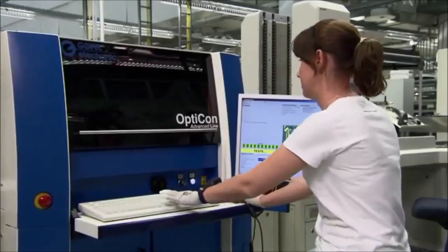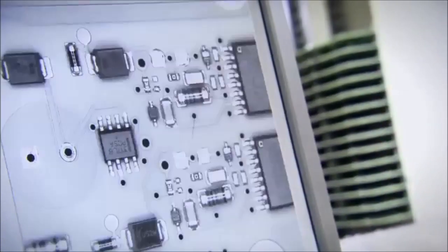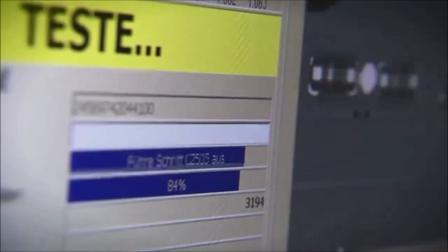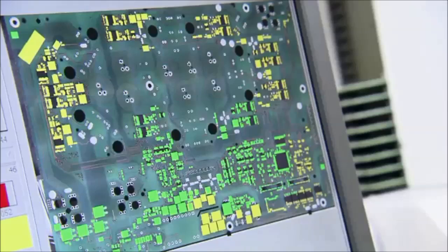Since inspecting small SMD components with the naked eye is not possible, SMA uses an industrial image processing system known as automatic optical inspection to check the predefined parameters quickly and precisely. During each test, 80 images are captured using a special camera. The system then compares these images with reference data in memory, so as to determine possible deviations. In doing so, about 1,600 attributes are checked.